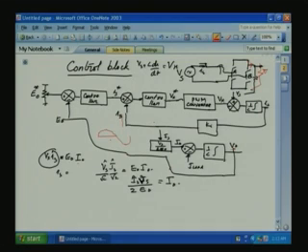That is one of the simplest ways of doing it. Otherwise, there are other ways to convert this converter alternating current to the DC equivalent and then do the control, but then you require other signal processing. So, here we assume the PWM action is so fast that during that small moment, IS reference and IS feedback, sinusoidal feedback, are not changing.